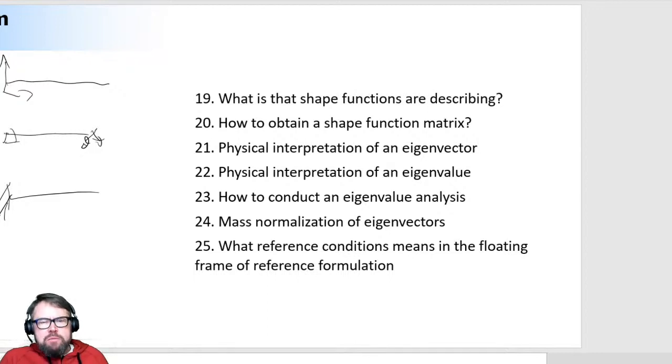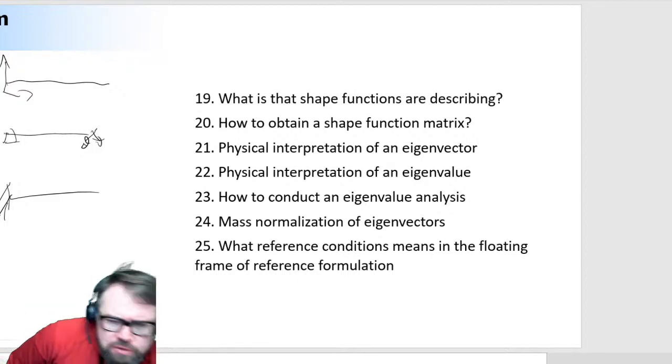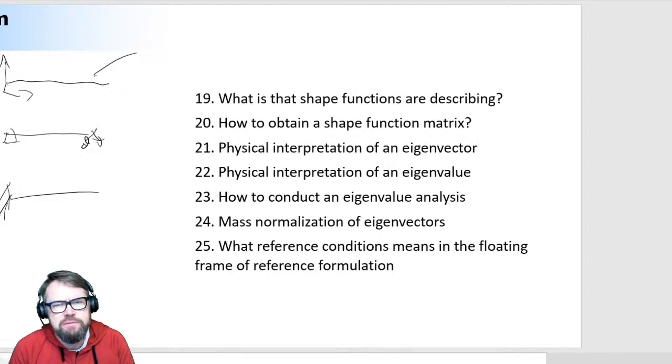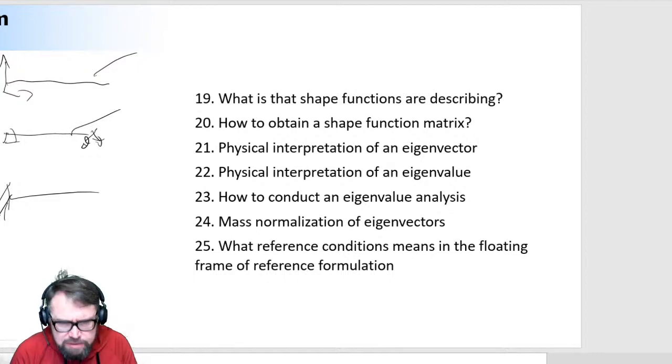By the way, this example about this connection rod is quite amazing, that you can select the reference condition any way you want. It's a little surprising because in linear dynamics, you know that if you compute eigenvalues associated to free boundary condition, the eigenvalue will be different when comparing the case with simply supported beam, which will again be different when comparing that to fixed boundary condition.